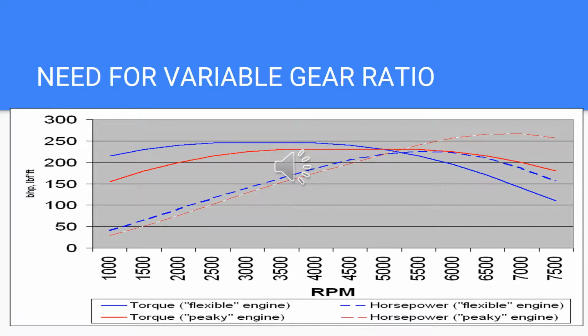Engines typically operate over a range of 600 to about 7000 rpm, although this varies and is typically less for diesel engines, while the car's wheels rotate between 0 rpm and around 1800 rpm. Furthermore, the engine provides its highest torque and power outputs unevenly across the rev range, resulting in a torque band and a power band. Often the greatest torque is required when the vehicle is moving from rest or traveling slowly, while maximum power is needed at high speed.